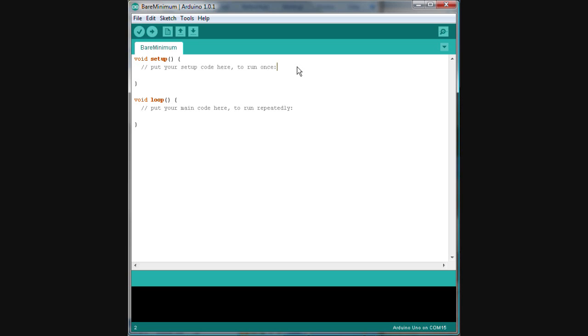So to start this serial communication, we need to set it up here in void setup by saying Serial.begin, and you see those both turned orange when I typed them correctly. We also need to tell it what speed we're communicating at. This is sort of just a technical detail, and for the most part you won't need to worry about it when you start programming with the Arduino, and you'll just type 9600 in here. It's sort of the default we'll be using for now. So we got Serial.begin(9600), which tells the Arduino we want to communicate with the computer using serial.